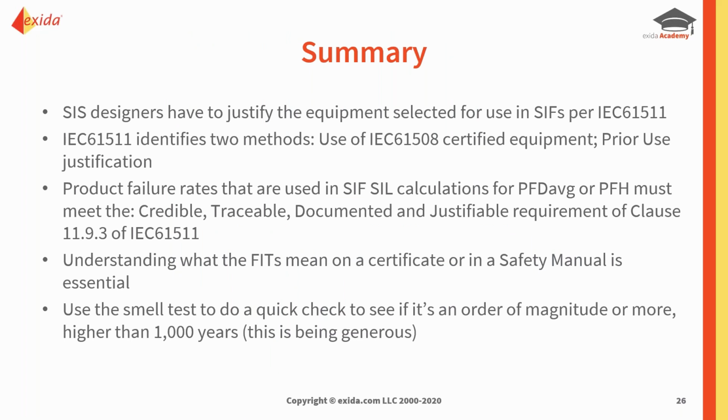So let's just summarize. SIS designers have to justify the equipment that's selected for use in the SIFs per 1511. And as I've said, there's two methods of doing that. There's use of certified equipment to 1508. And here again, even if it's a certificate for a device, you need to be able to look at those failure rates and see, okay, do they match up to the credible, traceable, documented, and justifiable? Or you do the prior use justification. Those are the only two methods.